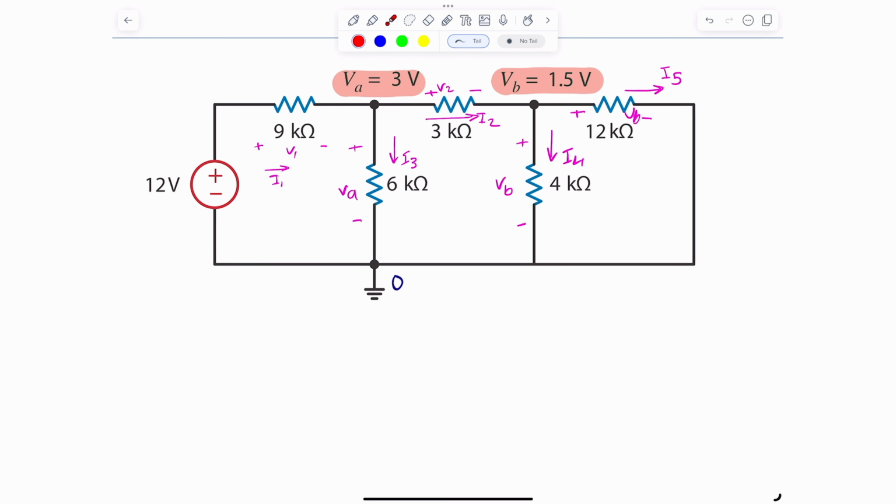And just a quick comment about how I decided the voltages and the current directions or polarities. For the voltages, if I know it, I just put it. For example, I know that this is VB, I know this is VB. If I don't know it, I just assume, for example, here this is V2, this one is V1. And when I assigned the currents, I made sure that all the currents are hitting the positive. So in here, it's hitting the positive. In here, it's hitting the positive. In here, it's hitting the positive. This one is hitting the positive. And also this one is hitting the positive. My rationale is that when I'm dealing with passive sign convention, I will not have to put negatives everywhere.